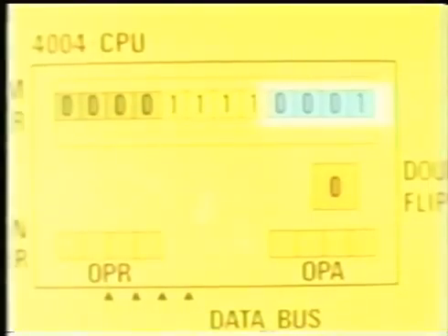The program counter now has been automatically incremented by 1 to 241 in preparation for fetching the next byte of instruction. During M1, the 4-bit opcode of the instruction stored in location 240 is transmitted to the OPR register in the CPU. During M2, the second half of the instruction stored in location 240 is transmitted to the OPA register in the CPU. This value will later be used as the high 4 bits of the jump address.